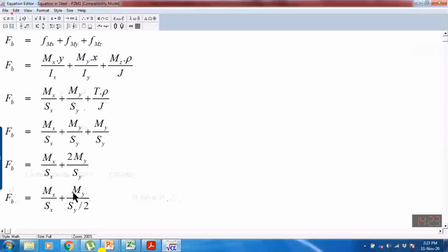It is like having a glass: half the glass capacity is for the torsion and half is utilized for the bending moment about the y-axis. That is the simplification. We are not computing the torsion stresses directly, but we are assuming that torsion stresses are the same as the stresses produced by My. In other words, we assume half of the capacity about the y-axis is for the bending moment My and half for the torsion stress.